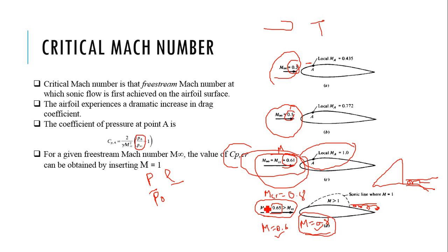So if we extend the critical Mach number, that is, if we get a larger critical Mach number, the shock over the airfoil will sit like this, so that only over the trailing edge region will we get some amount of separation, which won't affect the flow over the airfoil.